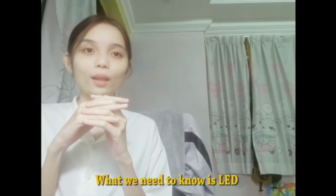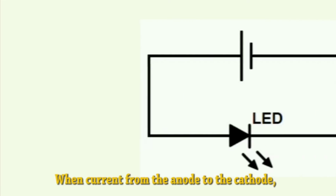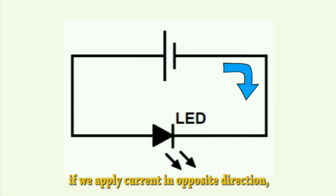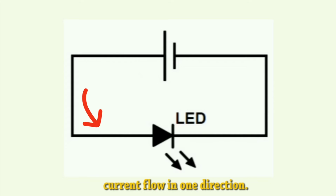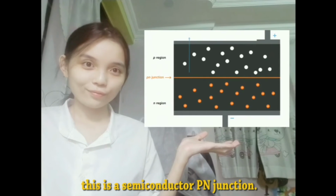What we need to know is that an LED only emits light when it is forward biased. When the current flows from the anode to the cathode, the LED will be on. If we apply current in the opposite direction, the LED will not light up. Like other diodes, an LED allows current to flow in one direction. Normally, these diodes are formed by a p-n junction. This is a semiconductor p-n junction.